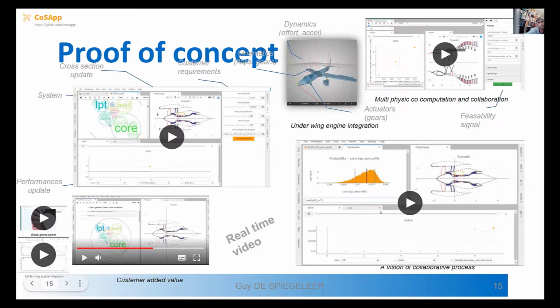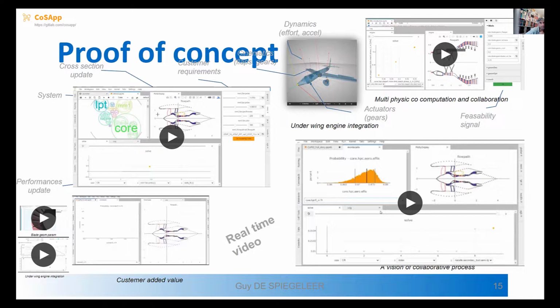So it increases the temperature of the combustion chamber. And of course, when your engine is getting old, the efficiency is going down, so you need to put additional fuel to respect the thrust. So it increases the temperature. It's what we call the EGT margin. So this is what the customer wants to know: the temperature at the turbine. So it is now evaluating the 2,000 engines.